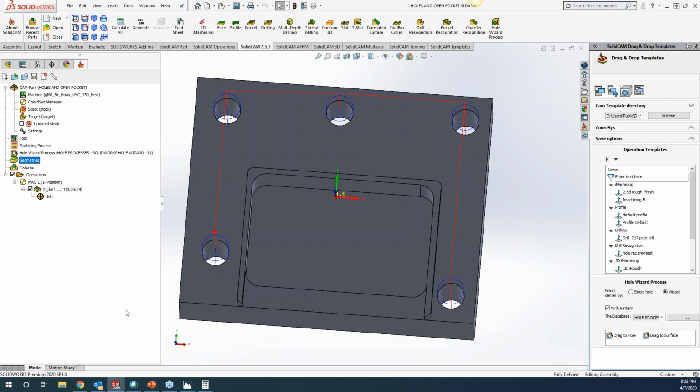Yeah, just make sure you keep an eye on what's being removed, because if you have tools in your tool table that aren't assigned to any particular operation, but you want to keep them in there, and you hit that select all button, you will wipe out those tools. Yep. So just keep that in mind. Yep, great point. All right, any other questions with the drill geometry or associativity or configurations, anything like that?